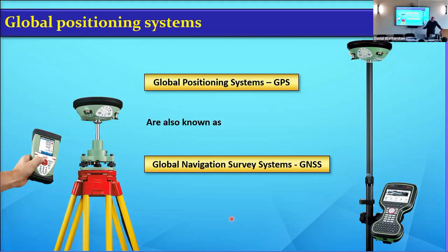And so I said to him, what's going on, John? What's the problem? He says, well, when they tendered for the job, they stated they were going to do it with GPS. So they did it with GPS. But as I said to you, the GPS is dependent on these satellites. So what was happening was the GPS position wasn't great, which doesn't really matter for a manhole cover before you put the pipes in, but it does on the heights.